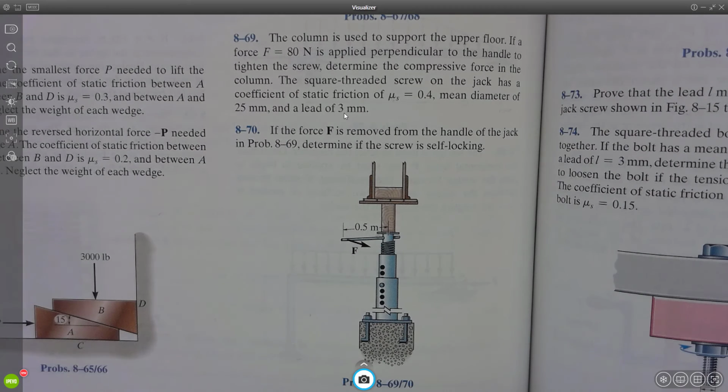Another place you would actually see this is when they're building high-rise buildings, like in downtown Portland, and they're pouring concrete floors. Skyscrapers have concrete floors going all the way up. Well, how does that work? They're suspended, with rebar or cables that tension those slabs so they don't just fall in. But while they're curing, they have to be supported underneath. So you'll see a ton of Lally columns that hold that floor up while the concrete cures, and then they unscrew them and take them out.